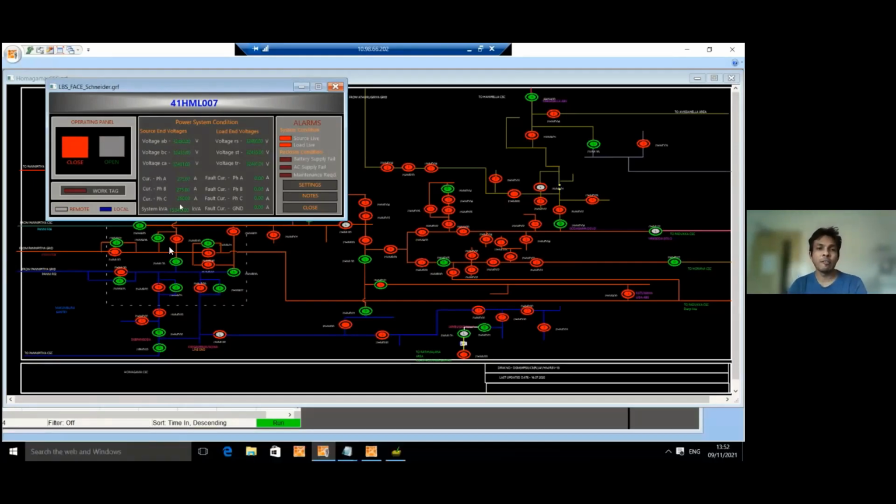Now, like I said, you always have the ability to monitor or read the data available in those equipment, maybe a meter, auto recloser, or that meter. As you can see, you can read the voltage, currents, etcetera, and you have the ability to switch on and off. Maybe if it is a smart meter, you can even disconnect.